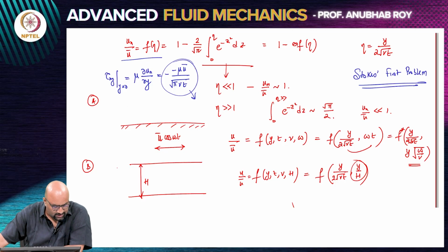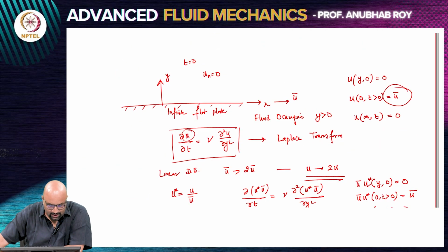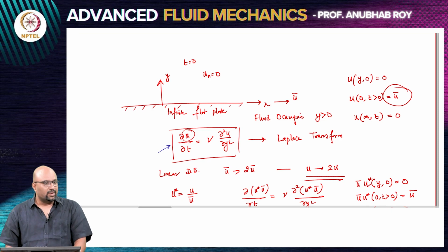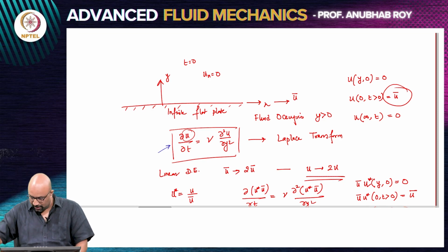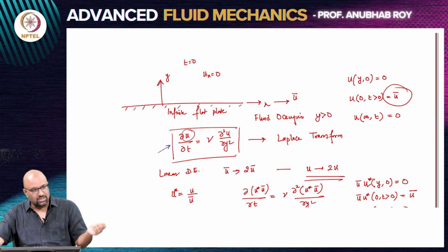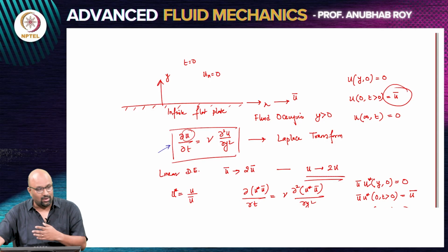So we solved the unsteady momentum equation with the assumptions basically being that we are looking at rectilinear flows, flow which is also two-dimensional. So we end up with an equation which bears similarity to the heat conduction equation. For this particular problem, we had no inherent length scales or time scales. There was a velocity with which I dragged the plate. The plate is infinitely long, and because it is infinitely long and you are doing this impulsive motion, you are not introducing any length or time scales in the problem.